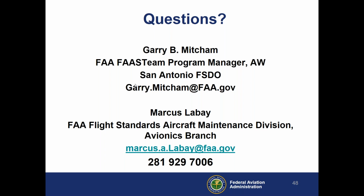So for training programs and such, I actually tell people the training program needs to be tied to the static test set, perhaps more importantly than just the transponder test set, because they could be sitting there without running a transponder test. And if they've got the system up at a different altitude and the transponder turned on, they're on the air.